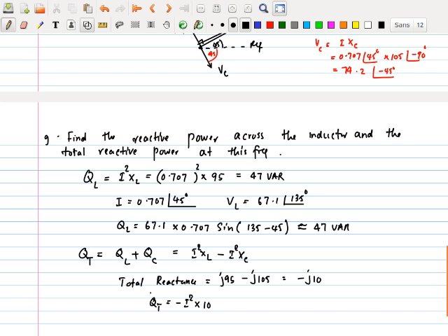So when you see this minus reactive power, what you are going to think in your head is what? This system is more capacitive than inductive. Because if you have minus reactive power, your system is going to be a capacitive system, and for inductive systems, this reactive power is going to be greater than 0.